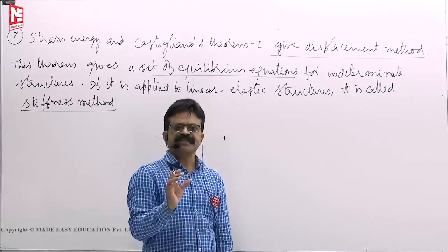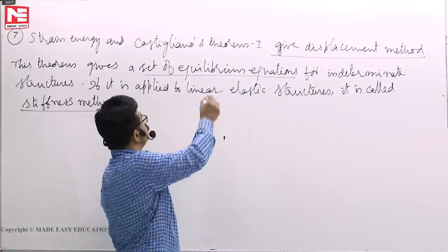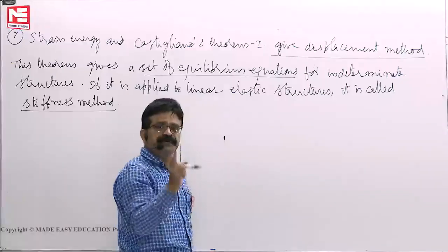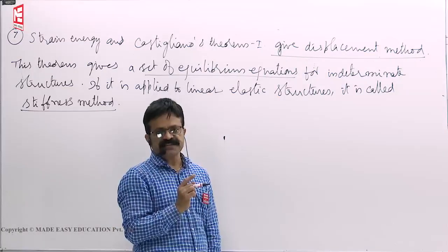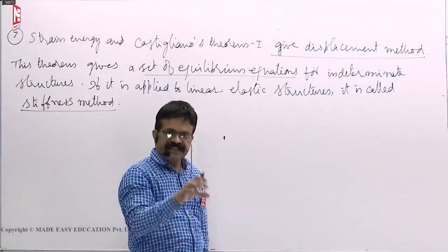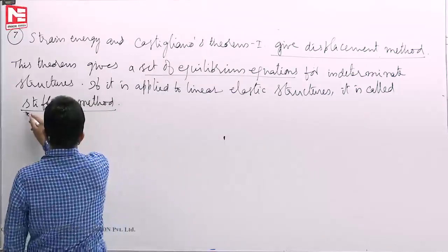So displacement method is a general term, applicable to linear and nonlinear elastic structures. If you apply theorem 1 to linear elastic structures, what you get is called the stiffness method of analysis.